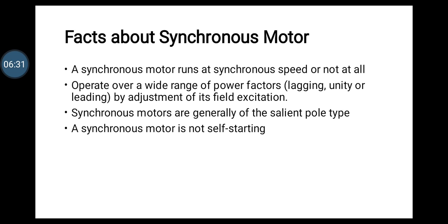The only thing is, to obtain this wide range of power factor, we need to adjust the field excitation. Therefore, a synchronous motor can be made to carry a mechanical load, which may be any pump, lifts, hoists, whatever it is, at a constant speed. With respect to any load, the speed will not change, so it will maintain a constant speed.